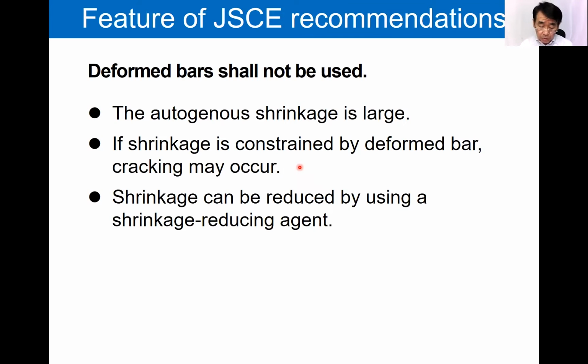Of course, we know the autogenous shrinkage can be reduced by using some technique such as a shrinkage reducing agent, but unfortunately, they are very expensive or they are still at the research level.